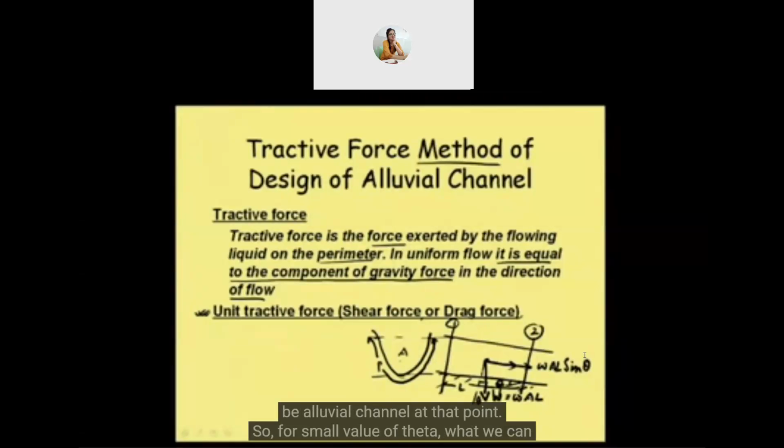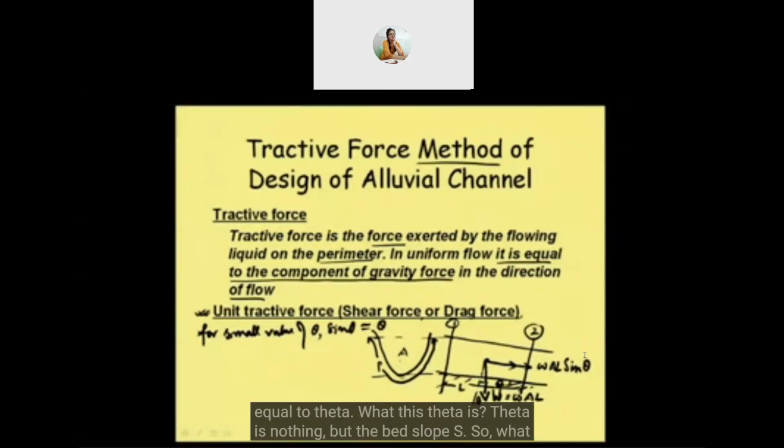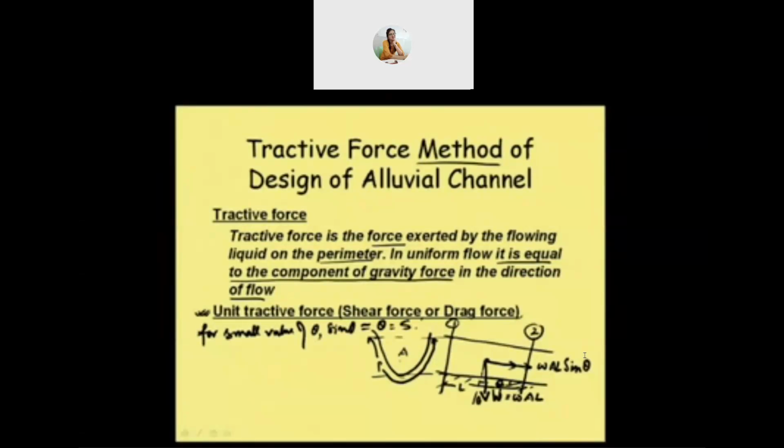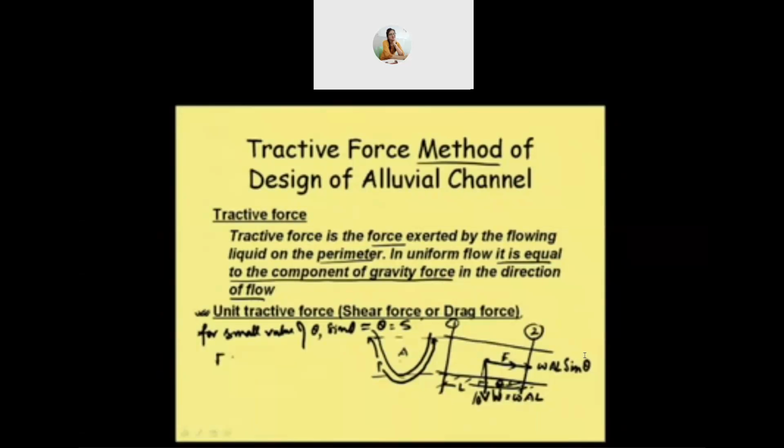So for small value of theta, in WAL sine theta, we can have sine theta approximately equal to theta. And what is this theta? Theta is nothing but the base slope S. So if this force is written as F, then F is equal to WAL S.